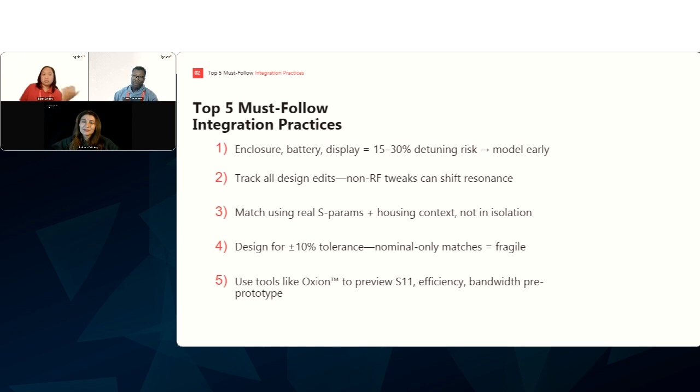And for wearables, you mentioned the effect of the body, simulation solver setup and phantoms matter. The way you connect, phase correction, and ground plane extension also matter. And lastly, you mentioned it's difficult to simulate and measure accurately. We have to iterate back and forth. We kind of covered some of these points, but I just wanted to put that on the table in case you wanted to add anything.